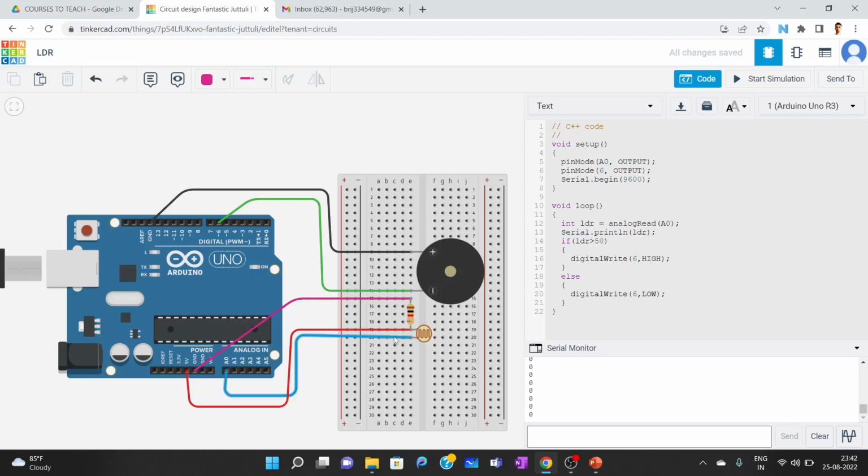One end is connected to the blue wire, which you connect to A0, and the red wire you see is the input voltage that is supplying the power to it. It's coded in red color. This resistor is connected with our LDR to manipulate the amount of current going inside the LDR system. One end is connected to the LDR and the other end is going directly to the ground terminal. You can follow the pink line. Now let's go to the coding part.